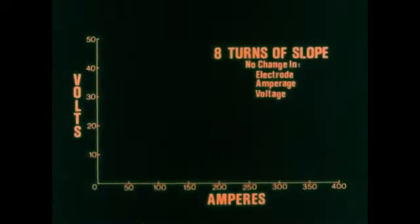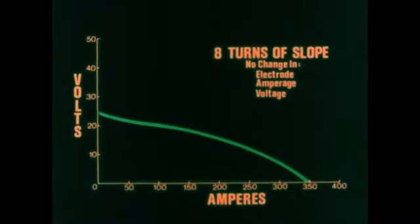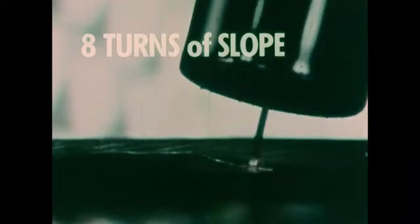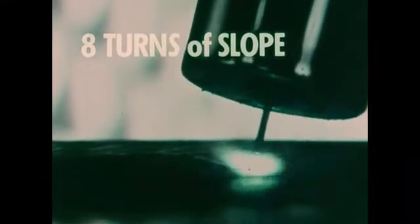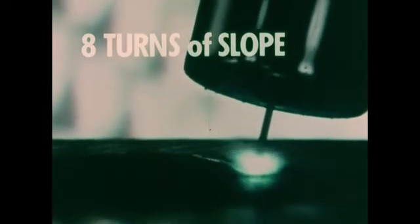By slowing the power source's rate of response and limiting the short-circuiting current, a short-circuiting amperage level is maintained which provides a smooth melting of the tip of the wire, and at the same time achieves a steady response of the current as it reignites the arc following each short circuit. There is a smooth separation of the electrode at the point of contact with the base metal. The violent spatter has been eliminated. Note particularly the steady reignition of the arc immediately following the short-circuiting or contact occurrence.